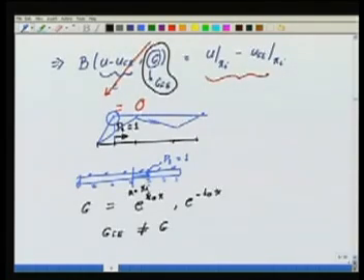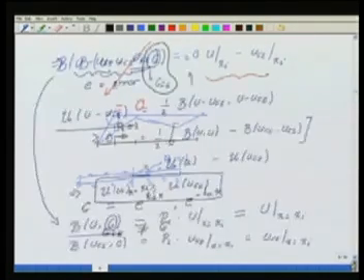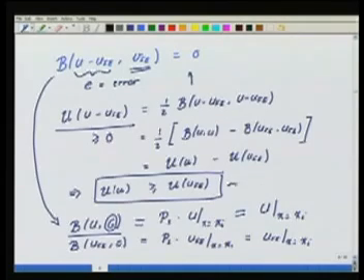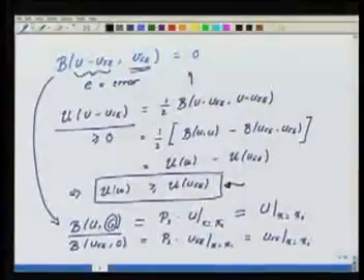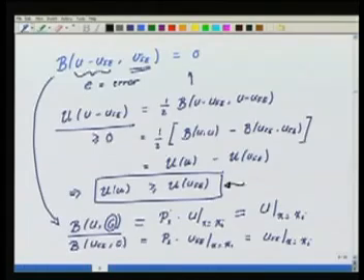Next, if I go back to what I had done here, this also gives us a way of checking what is happening. Okay. I know that my finite element solution has been obtained. How do I see that if I refine the mesh further, or I keep on increasing the P, I am doing the right thing, that is I am converging to the exact solution? That is through this.